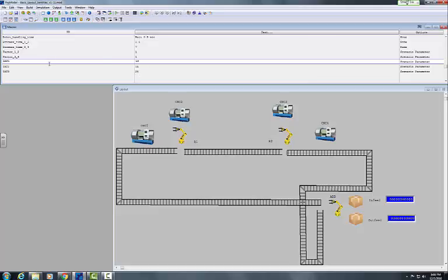It means that part 1 comes into the simulation model, the raw material arrives every 10 minutes. For part 2, the raw material arrives every 15 minutes. For part 3, raw material arrives every 20 minutes. And then if you keenly observe, we've used something called scenario parameter for these. I'll explain this once we run the basic simulation. So yeah, I explained the macros. This is something which we have not used.